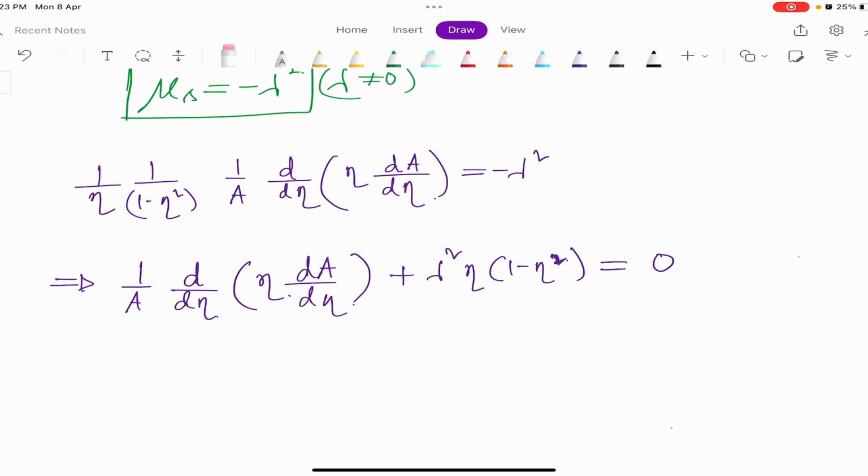Similarly, we can have the Graetz problem for the uniform wall heat flux case. Also, this was for a pipe. We can also have the same thing for a set of parallel plates. So a parallel plates channel can also have the same formulation, and that will be called the Graetz problem for parallel plate channels. Now let us take the same thing. I don't have to formulate the problem from scratch, because now you know what the assumptions are, and how to take up the problem up to this step, that is the formulation of the separation of variables.